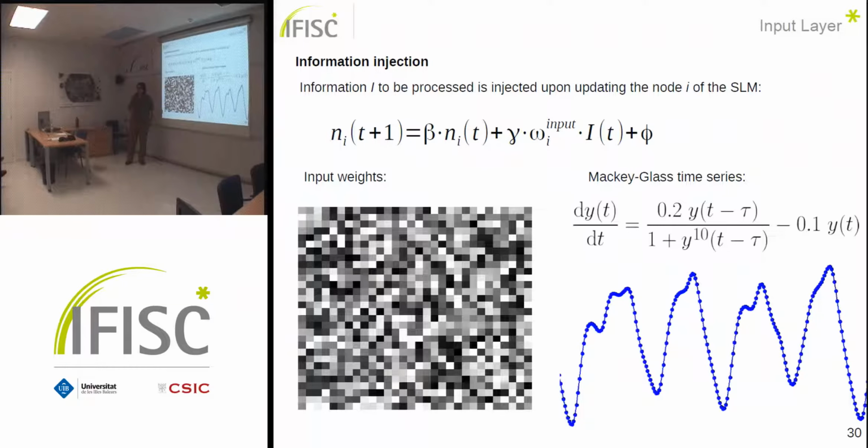There's this beta n plus part that was done by the computer with the feedback. I mean, this is the part of the feedback. Yes, and beta is what the computer changes electrically in the spatial light modulator. Yes, the computer is going to update the states of the SLM cells according to this rule. And it's going to use the information obtained from the camera, which will be an intensity measurement of what the camera records from the network.